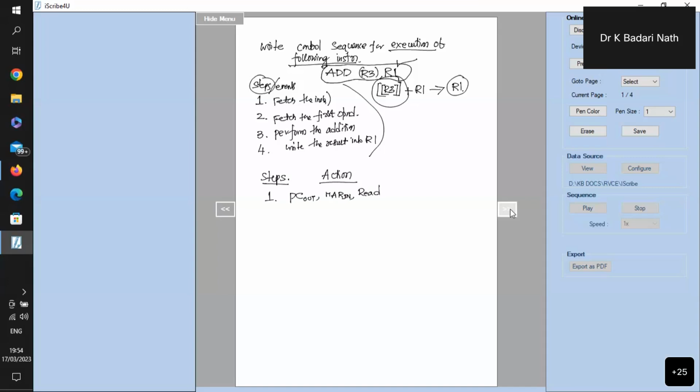At the same time, we have to make the program counter get ready for getting incremented. So we know that, we have to give a select 4. So instruct the adds for the addition, and also we will load the answer of the program counter, which is incremented by 4, into the Z register.